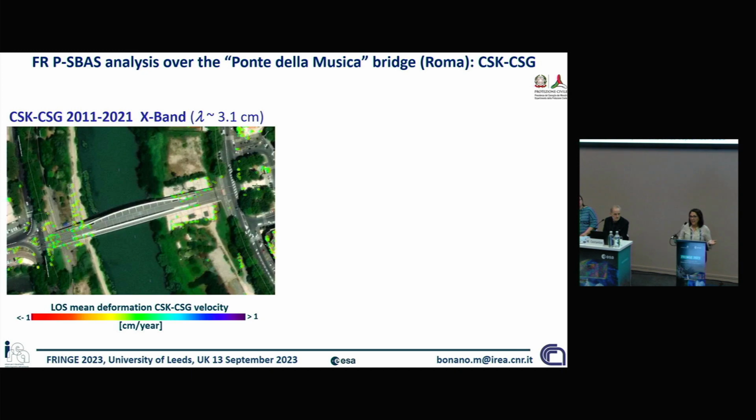So many cases where the X-band satellites work very fine and many deformation phenomena are detected, but we also have some cases where X-band is not completely useful to detect the deformation, as in this case. Here we have the Ponte della Musica bridge, and we can see that the deck of the bridge is blind, so X-band is not capable to detect the deformation.